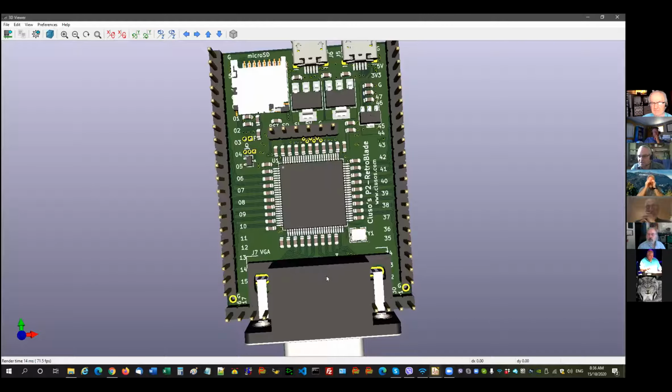Now the VGA uses the top 5 pins of the row along here. I did that so that I had the maximum continuity I could get of pin numbers. So the top pins here, we're going 23, 22, 21 and 20, and then pin 19. So 19 is vertical sync, and then you've got horizontal sync and RGB. So I shoved them out of the road instead of being down on an 8-pin boundary, they're on a 4-pin boundary, less 1.